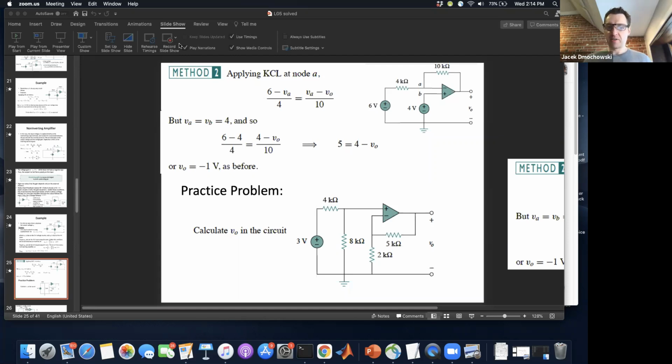But in many cases, the problem we're about to do is, actually, I think it's non-inverting. Basically, the most important cue is where the voltage sources are, and whether they are connected to the positive input or the negative input.